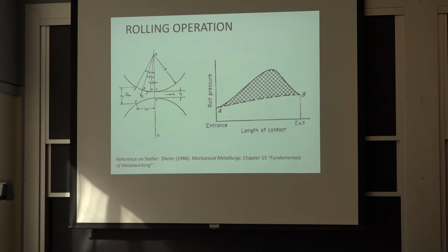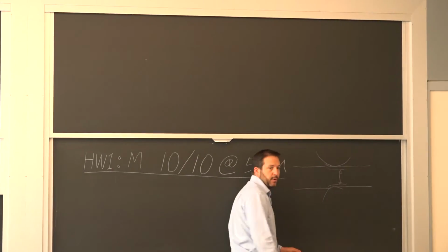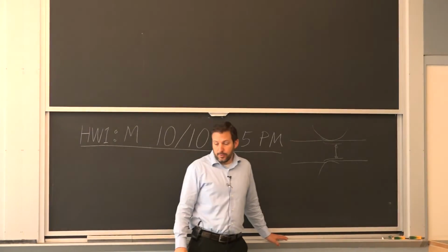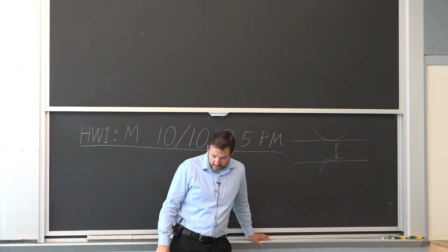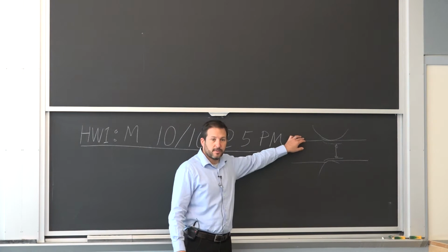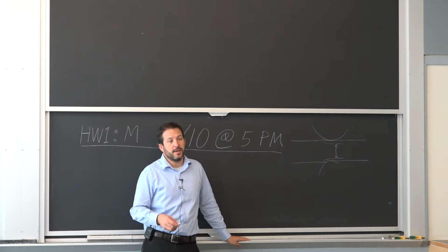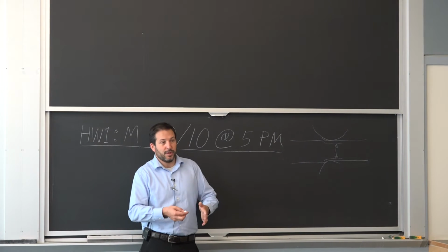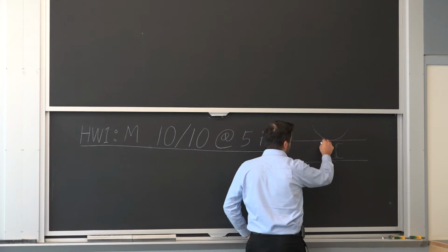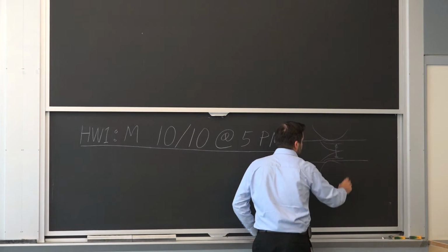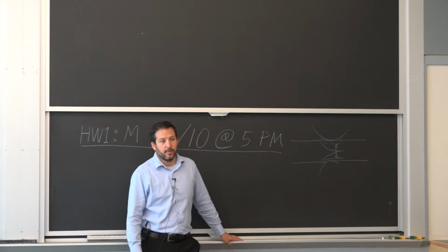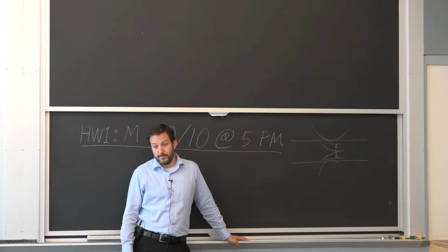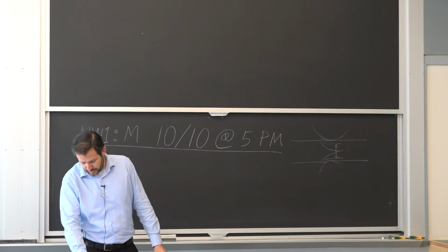So we have a roller here, and then we have another roller there. So what happens if it's not enough, your deformation layer is only in this area, and you haven't done any work in what's in the middle. And that will happen sometimes and lead to properties that are very, very different on the surface than at the mid-wall. So there is a minimum amount of reduction you want, so your deformation, your plasticity and stresses get all the way to the center and everything gets deformed. So it's not super common, but it will happen on products.